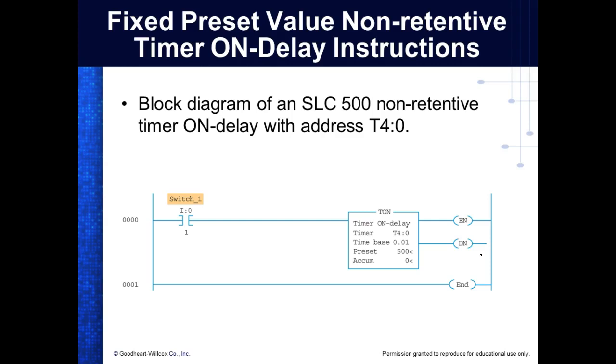And that's what we were looking at over there. So this doesn't define it as a switch. All this defines it as some device out there that is going to give me a 1 when it's true and a 0 when it's false. And it's going to be outside of the PLC. Everybody understand that?